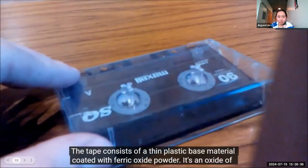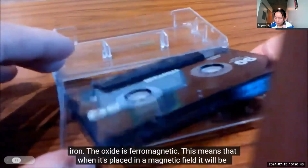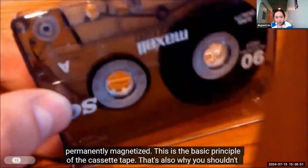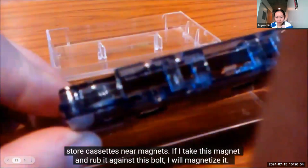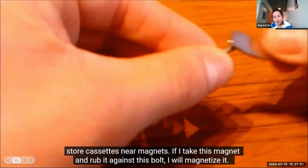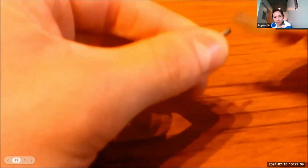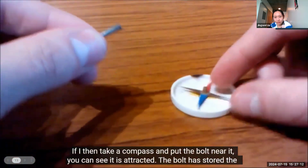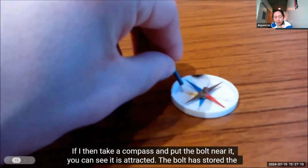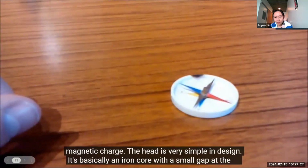The tape consists of a thin plastic base material coated with ferric oxide powder. It's an oxide of iron. The oxide is ferromagnetic. This means that when it's placed in a magnetic field, it will be permanently magnetized. This is the basic principle of the cassette tape. That's also why you shouldn't store cassettes near magnets. If I take this magnet and rub it against this bolt, I will magnetize it. If I then take a compass and put the bolt near it, you can see it is attracted. The bolt has started the magnetic charge.